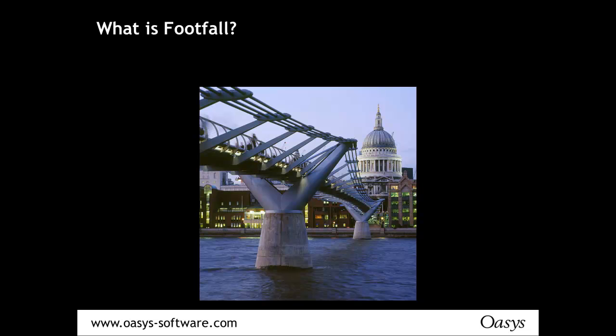A lot of people think about the Millennium Bridge when we talk about footfall vibration, but that was actually a horizontal footfall problem rather than the vertical footfall, and mechanically speaking is quite a different phenomenon. That was horizontal vibration, which means that pedestrians had to lock step with each other. They were forced to. You can't walk out of step with a horizontal vibration without falling over.